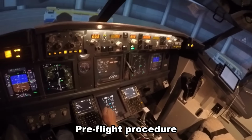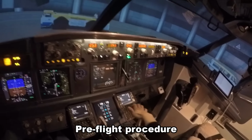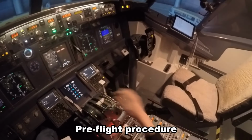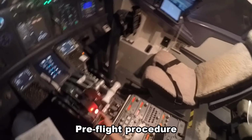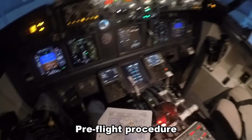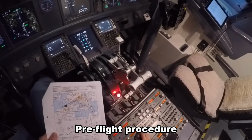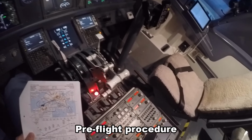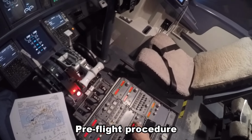The speed brakes are obviously down, flaps are 0, and engine start levers are set to cut off. Our parking brake is set. We'll just go to the pedestal, so we'll just set in our ILS frequency, which is going to be 110.9, and we'll have a transponder on to transponder code 7370.